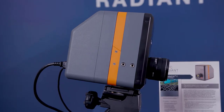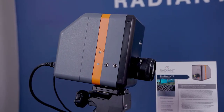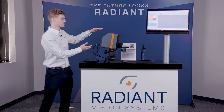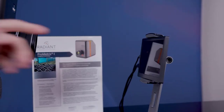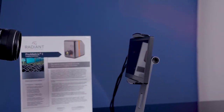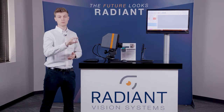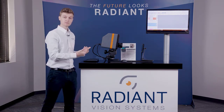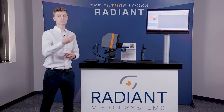Our solutions have two main components, the imaging colorimeter system and the software that runs the automated testing. This particular system right here is a scientific metrology unit. What that means is we're going to be able to measure luminance and color of a display. This particular system uses tri-stimulus filters. These filters are designed to replicate the response of the CIE color matching functions. And what that allows the system to do is capture data that represents the human perception of color and brightness.